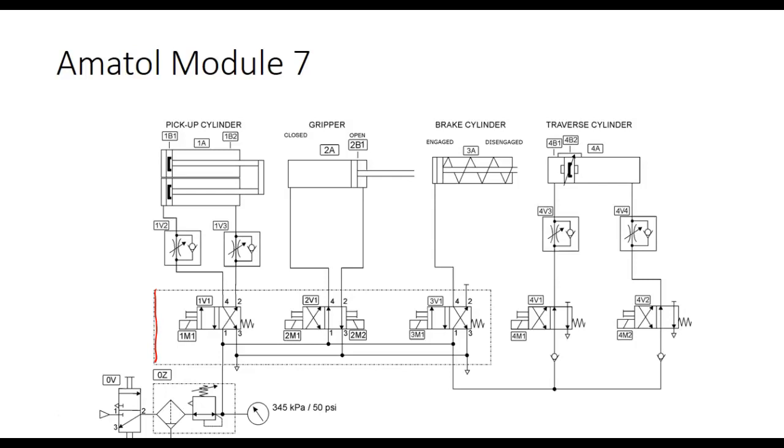They share the pressure and they share the exhaust. So all these valves are mounted on a thing on the bottom, and it's got the exhaust and the pressure. It might have two exhausts on both ends if it's using those 5-port valves, right? And then it's got the holes up here with the working ports, and the valves just mount onto the manifold.